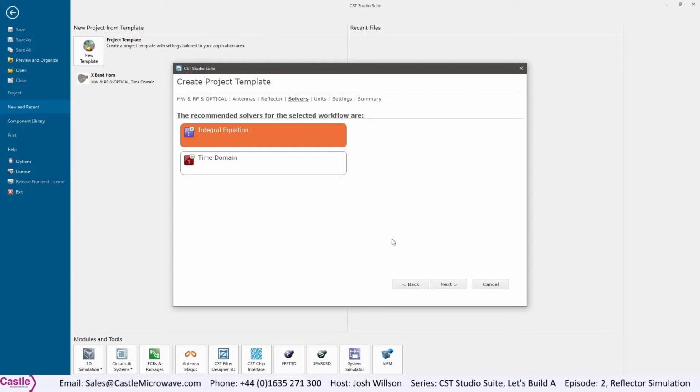The integral equation solver is available for plane wave excitation, discrete phase ports, discrete edge ports, waveguide ports, far field source excitation, and RSD current sources, as well as simultaneous excitations of them. The solver can be used to perform a characteristic mode analysis. Electric and open boundaries are supported. E-field, H-field, and far field monitors and surface current monitors can be set in the integral equation solver.